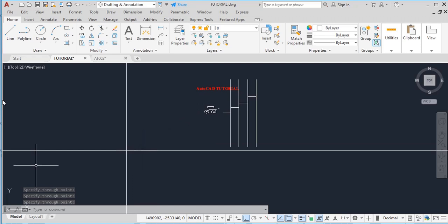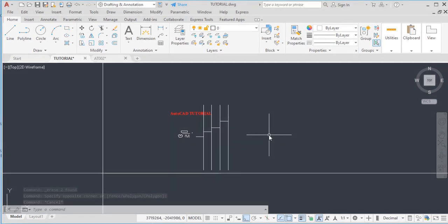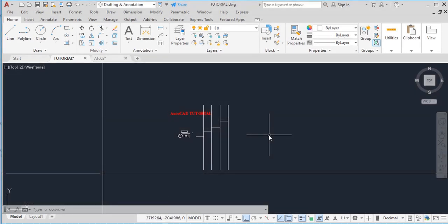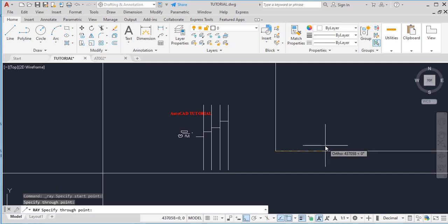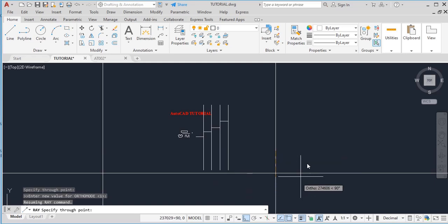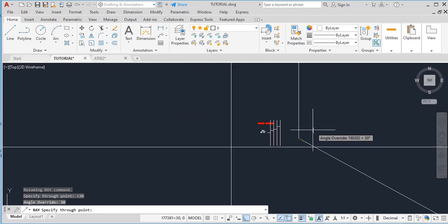The command will go off. So starting from this point we have this, the same thing, and this, the same thing. Again, even if you need to draw some angular kind of construction line using this same type of construction line, all you have to do is go back to that construction line, select it, say I want it at 30 degrees. All you have to do here is use shift and less than, just press it simultaneously, and then you type 30. Then once you click on enter, you're going to see the 30 degrees angle line there.